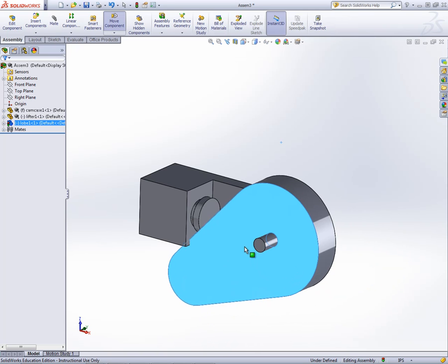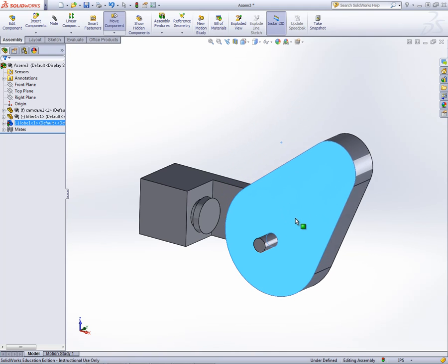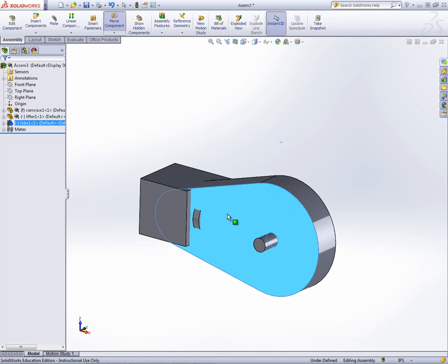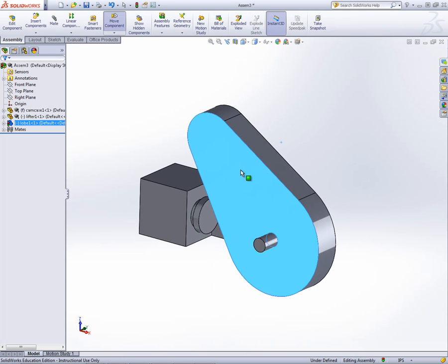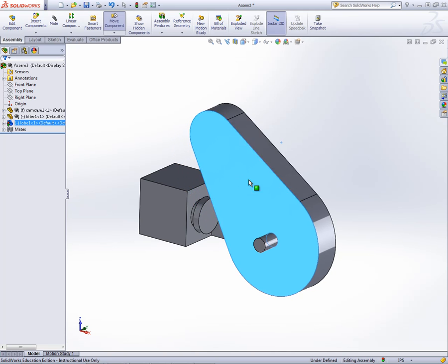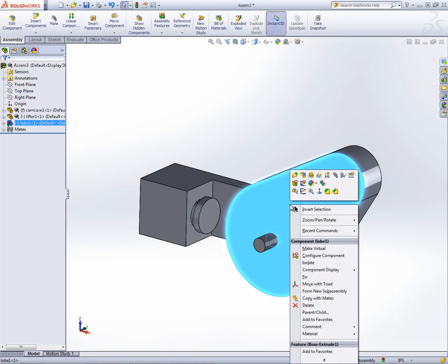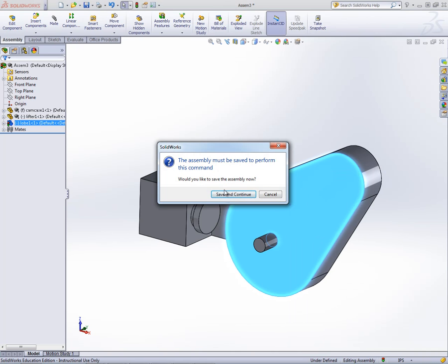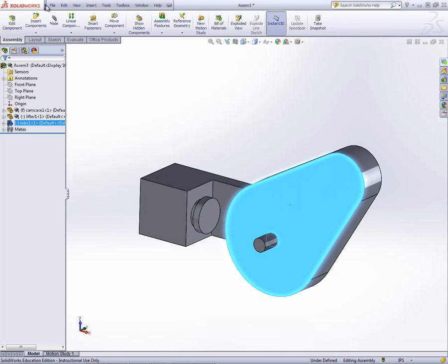case. Now if you haven't noticed already, we have a serious interference problem, and that's all part of this module. So we're going to go in and edit the camshaft lobe so that we are not having this part collision that you're seeing right now. So we'll move our cursor onto the surface of the camshaft lobe. We'll right click and we'll left click on Edit Sketch, and I need to save it first. So we'll go up and save.